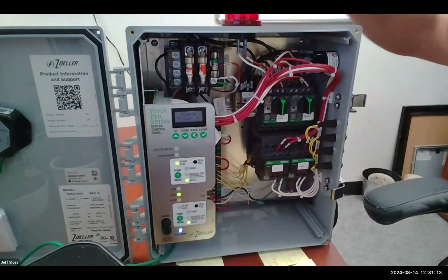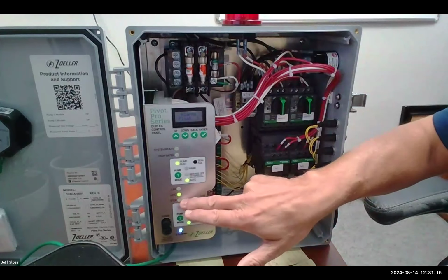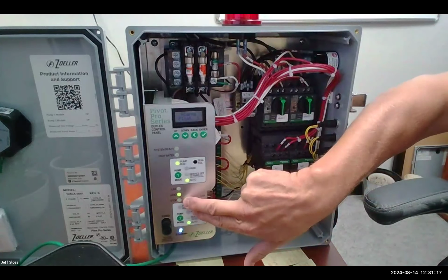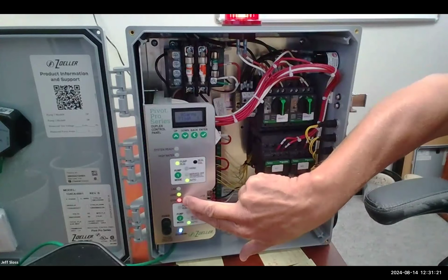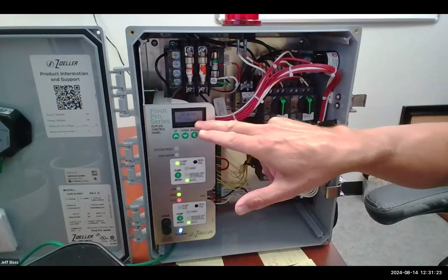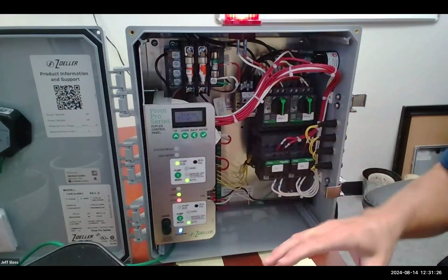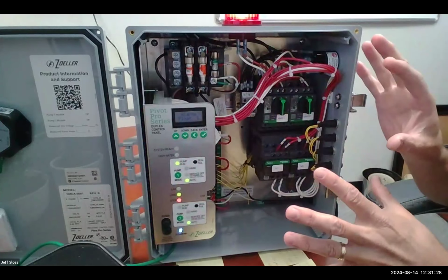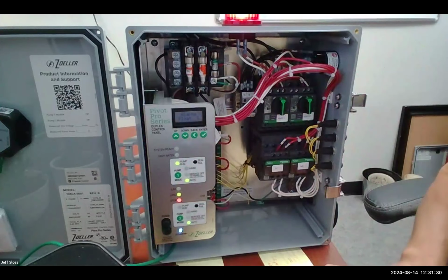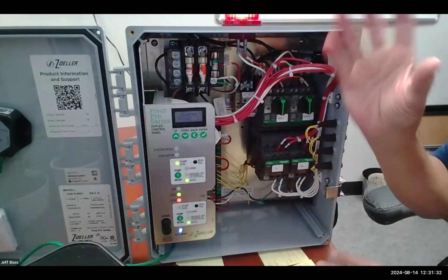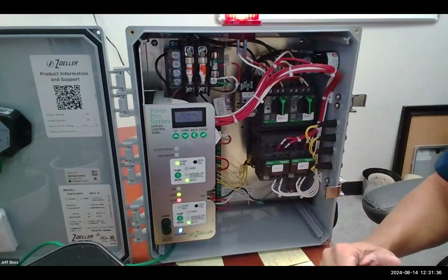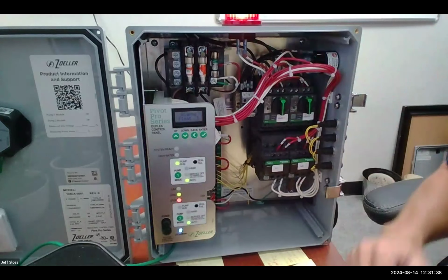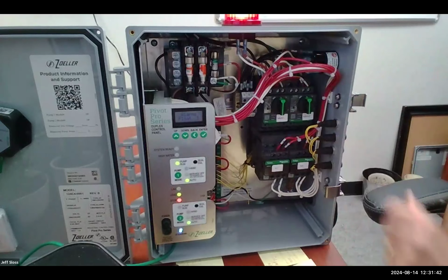The horn is going, the globe is blinking, and this stop LED, which is the lowest float, float number 1, is blinking red. And the screen says alarms, float 1. I'm being told exactly what's wrong with the station. And if this was connected to the cloud, my phone and my text and my push notifications are blowing up with float 1 faults. I know exactly what's wrong. This float is stuck. So now I can turn it off.